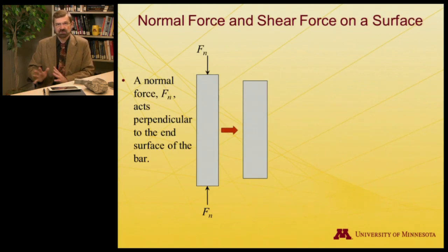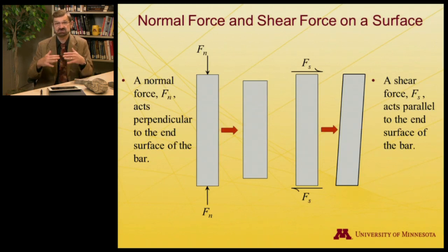So the first thing we want to do is look at forces as applied to solids, and we'll go from forces and eventually talk about how those relate to stresses on the solid. There are two types of forces that we normally talk about. There are normal forces shown here where you push on the end of the bar, and if you do that, the result will be that the bar becomes a bit shorter. And there are shear forces where you apply a force along the surface.